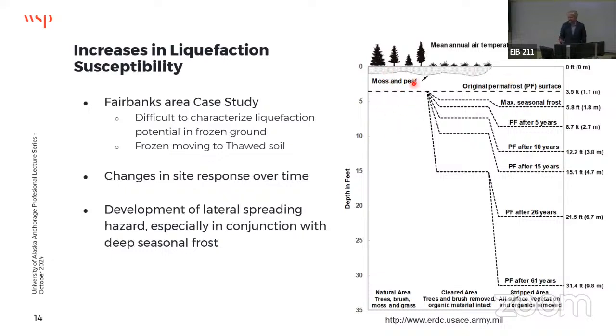Blow counts in frozen ground are pretty meaningless, right? You count them until you run out of fingers and toes because the blow count's really high. But at the end of the day, you discard the blow counts because you have a stiff material, it's frozen. But you take the sample, right? And the whole goal of driving that sampler was to take the sample back. So there's a number of issues that relate to this.